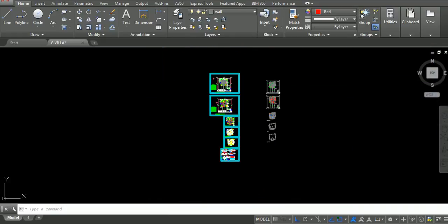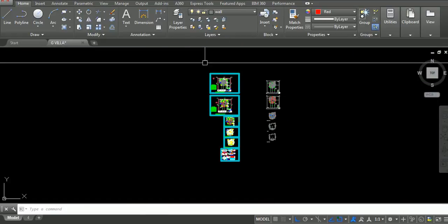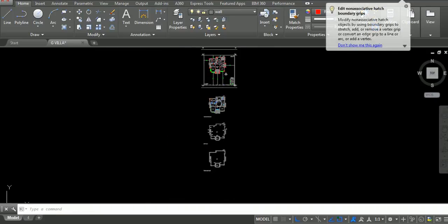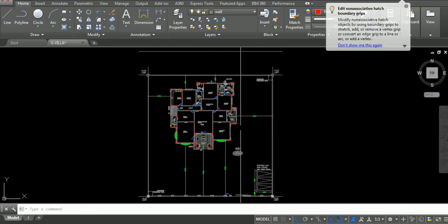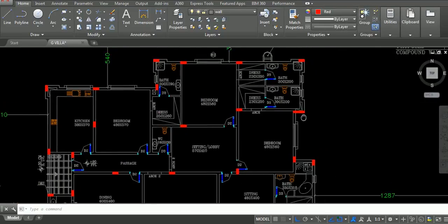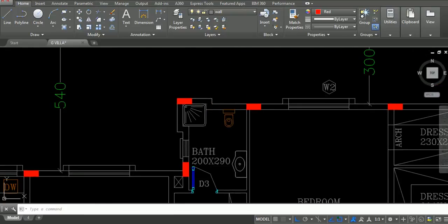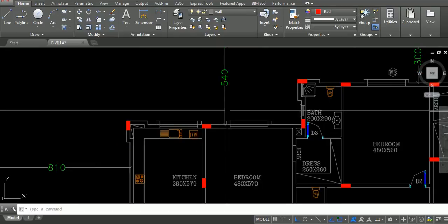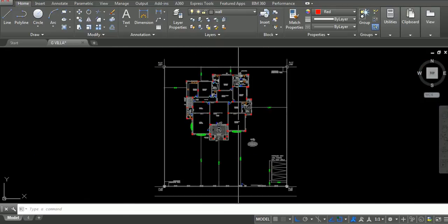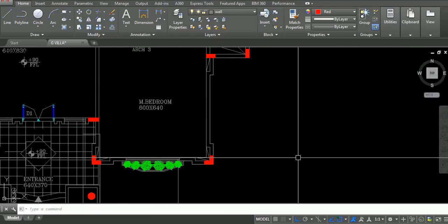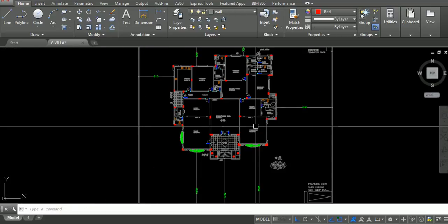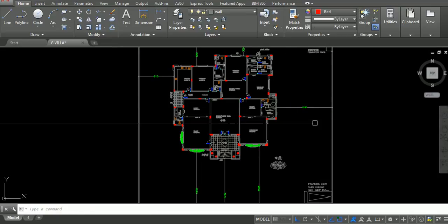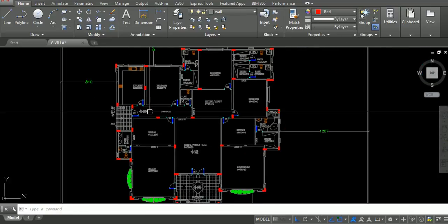Okay, let's start by bringing the architecture drawings from the architect. As you can see here, these are the architecture drawings. All the axes were removed and I placed the columns because we need the columns in our design. Sometimes the pipes will interfere with the columns themselves, so we'll have to remove the pipes, because for our design the structure always comes first. Unless, of course, there are big problems, then we can discuss with the structural engineer in order to move some columns.